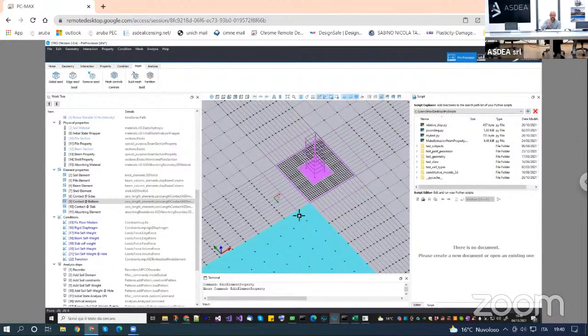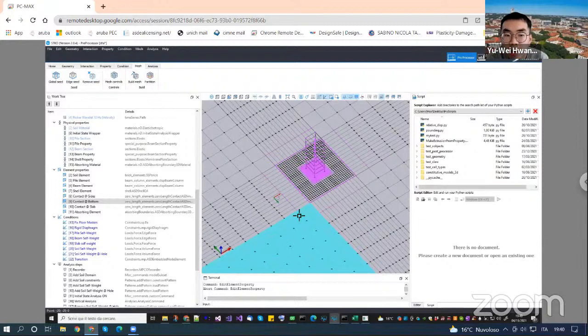Just to summarize, I implemented the element in such a way that I can update the shear modulus. The real problem is how do you compute the shear modulus of a nonlinear soil in such a way that it is meaningful. One thing that can be meaningful would be the secant modulus. But how do you get the secant modulus from any constitutive model? If you start with PDYield02, it can allow you to specify the modulus reduction curve you want.